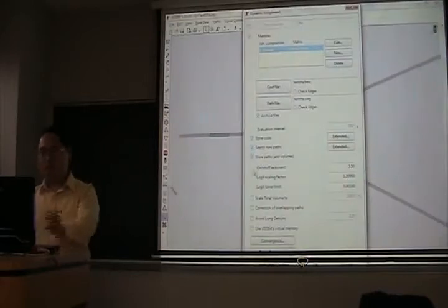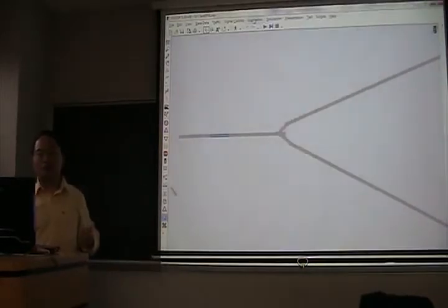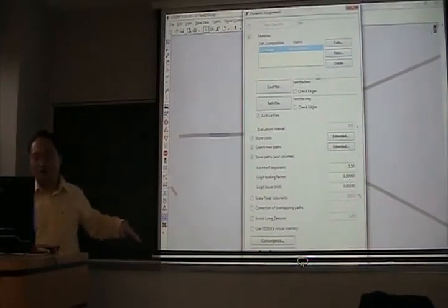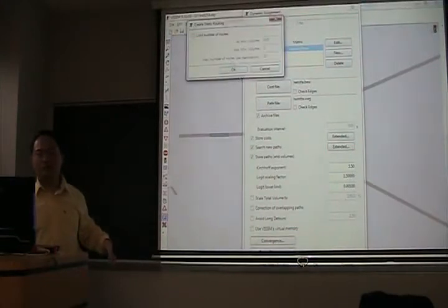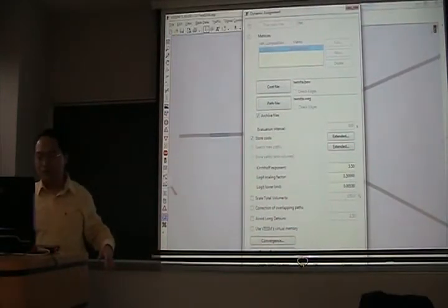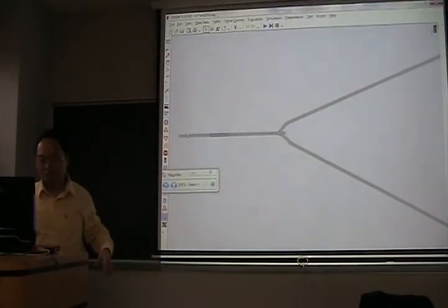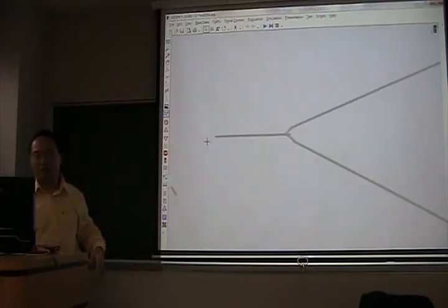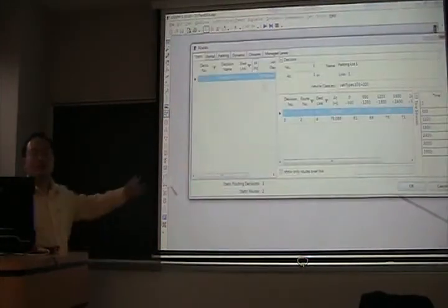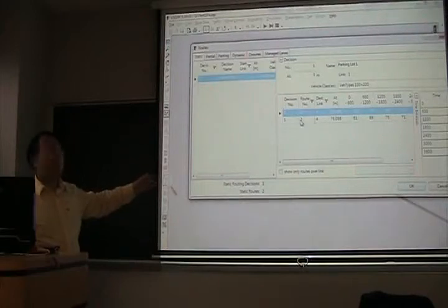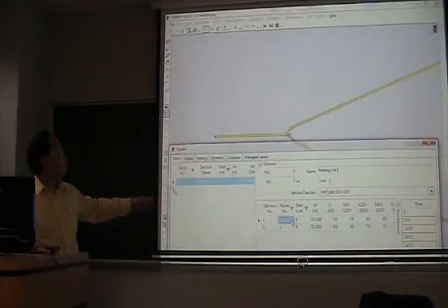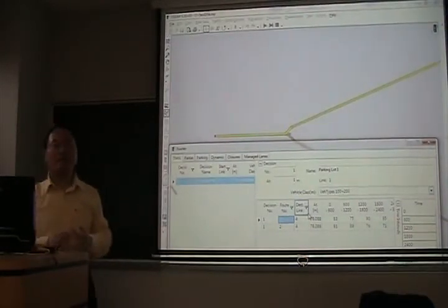So we use dynamic traffic assignment, and we found 2 routes, the upper one and the lower one. If we use this create static routing, then I just created 2 routes, static routes, like what we mentioned in the first lecture of VSIM. See, these 2 routes are converted from the result of dynamic traffic assignment.